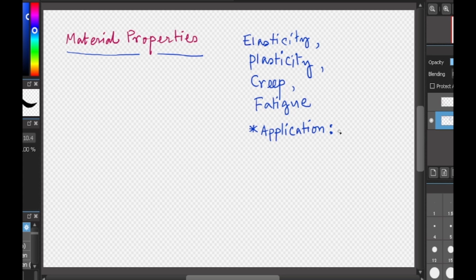Okay. So for axial loading like tensile or compressive, the universal testing machine or UTM is used. In case of ductile material, the yield point is very precise, so we can find it at a particular and specific point, while for brittle materials, the point of brittle fracture under tensile load is noted.